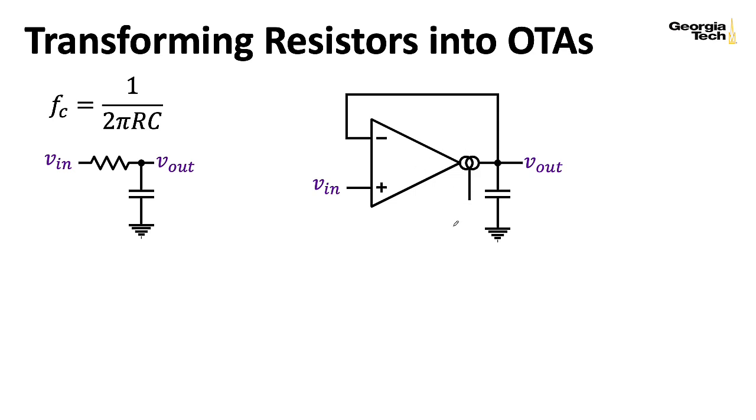Now, in all of the schematics I'm going to show you in this lecture, I'm drawing the current control pin here, but I'm not going to bother drawing the rest of the current control generation circuitry. It's some sort of voltage-to-current converter, usually either linear or exponential in its characteristic, usually exponential for a VCA. As is our usual convention, I'm assuming that we're measuring this output voltage with some high impedance device, so no current is flowing into whatever we're measuring the output with.